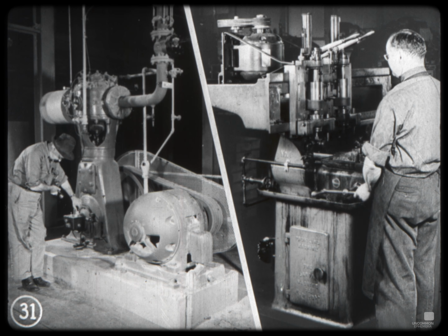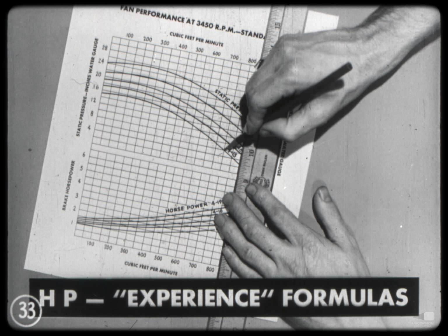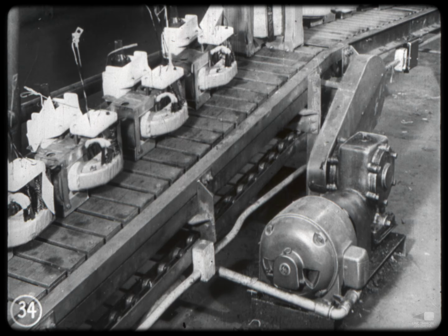Other mechanical formulas have been compiled to determine the horsepower required for compressors and electric drills and for lathes, punch presses, and the like. In some cases, the motor horsepower is determined by so-called experience formulas, such as the one in this fan manufacturer's handbook, which shows what motor horsepower is needed for a certain set of conditions. In developing these formulas, manufacturers run tests on motors driving many machines of the same type, and from the information gathered, they compile general formulas.